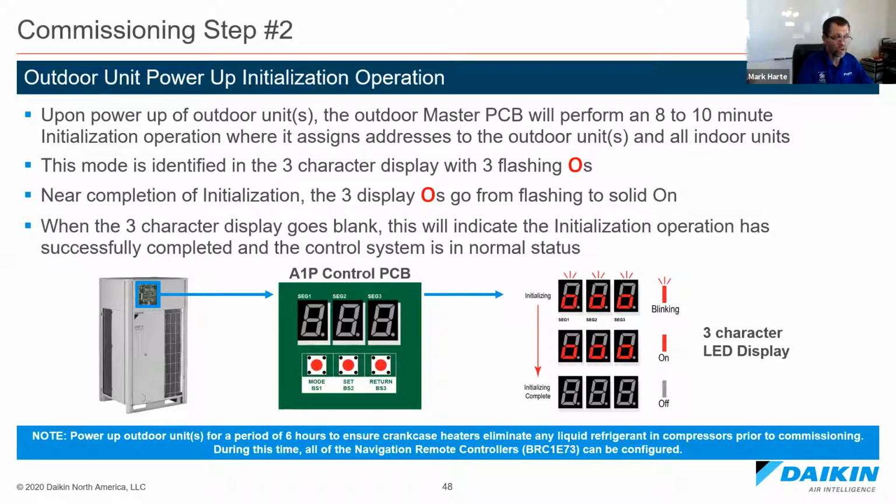There's also refrigerant recovery mode. You can go to that outdoor unit, and it's a sequence of buttons you hit. What it will do, it'll open up every expansion valve at the BS boxes, at the indoor units, and at the outdoor units. It gives you a wide open refrigerant circuit.